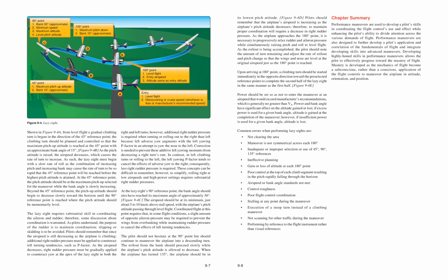Execution of a steep turn instead of a climbing maneuver. Not scanning for other traffic during the maneuver. Performing by reference to the flight instruments rather than visual references.